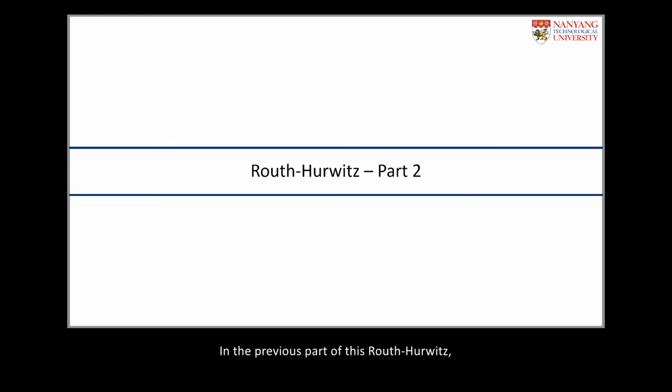In the previous part of this Routh-Hurwitz discussion, we have already discussed how to check if the system is stable or unstable. Just to refresh our memory, if all of the numbers in the first column have the same sign, then your system is stable.